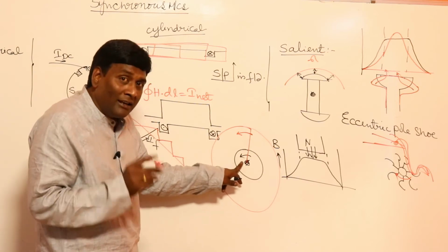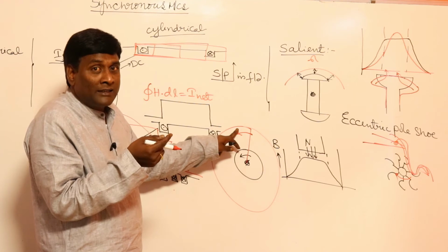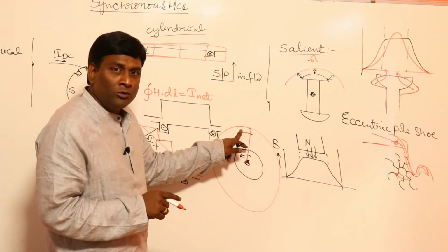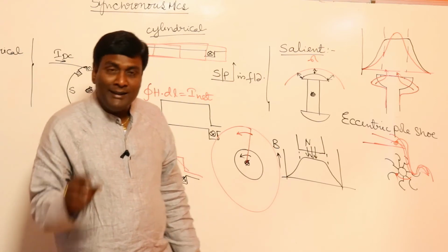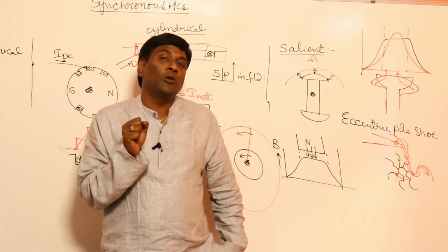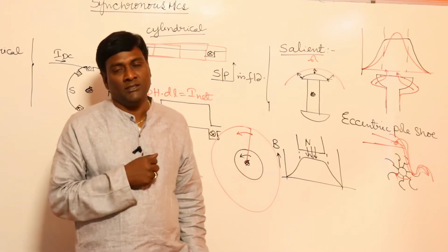So here black is revolving 1 revolution per second, red is revolving 1 revolution per second, but the radial velocity of red will be more, because of 2 pi r. The moment radial velocity is more, automatically mechanical stress, centrifugal forces, will be more on the insulation.